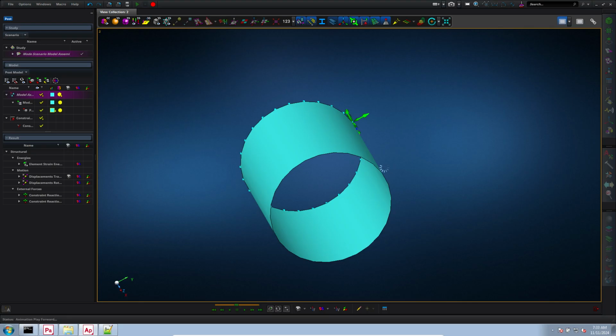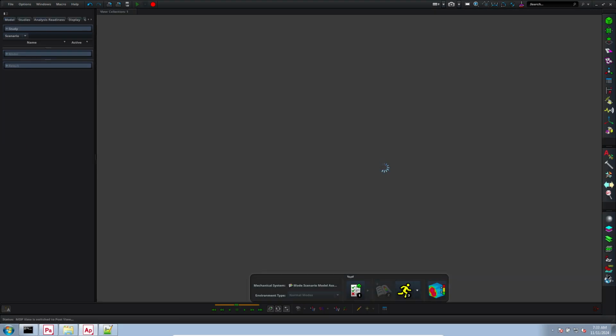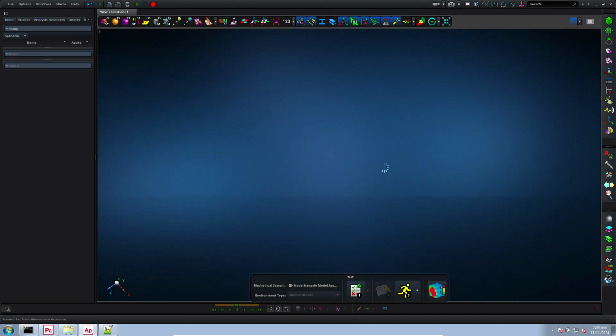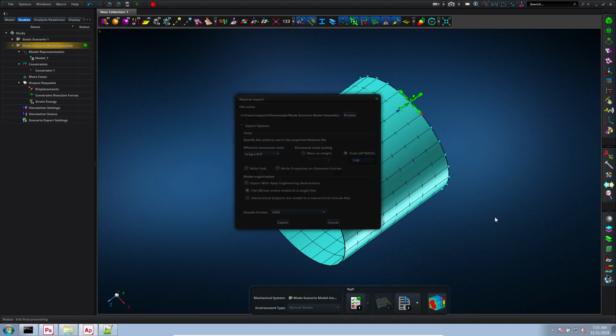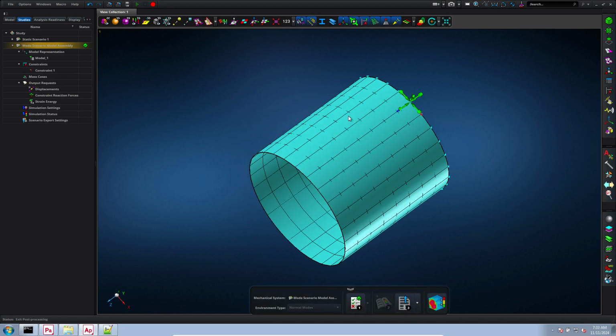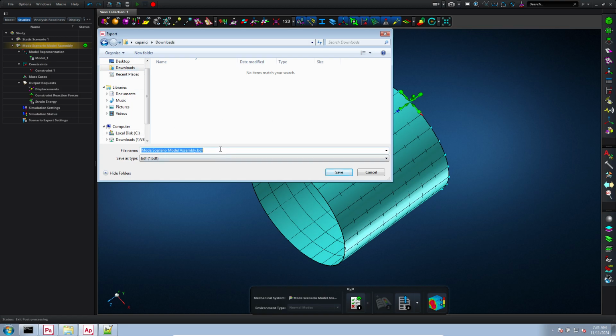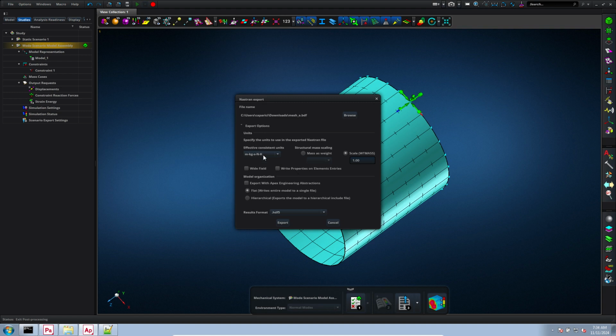I built the mesh really quickly in MSC Apex, but now I've been asked to configure this in Patran. So what happens now? Here, click on this button here, and then click on this button, Export BDF. This is where you can output this mesh. So let's go ahead and call this mesh A. And then we'll select the units that we want to use. We'll click export here.